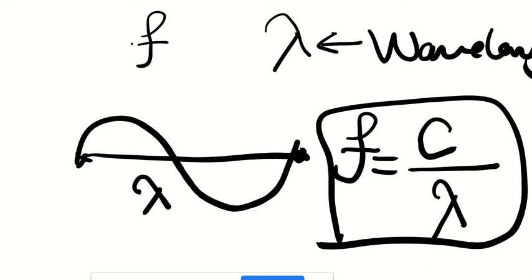And then, when you have a signal going through a transmission line, the signal doesn't have the speed of light anymore because of all those dielectrics that are inside. For example, for coaxial cable, you have Teflon, so that would decrease the speed of the signal.